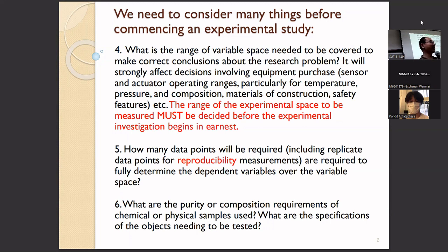That means this sensor cannot reproduce. You check the system, which is the same, and then you check the temperature of your system today and tomorrow. If you get the same result, okay, your sensor is reproducible, but whether it is accurate or not, you have to check against the standard. This also means reproducibility.